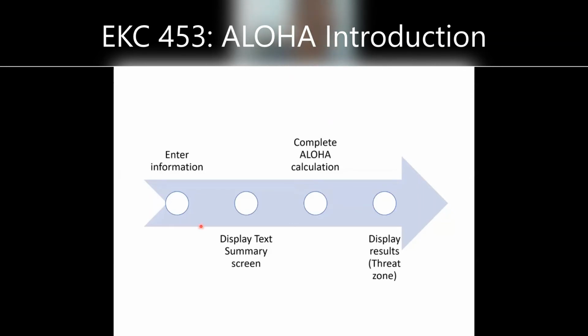If you are interested, or if the chemical you want is not listed, or the product of your plant design is not listed in the library, you can introduce or modify it. You can add other information for that chemical so that you can use it in ALOHA. ALOHA will determine whether, if there is a gas dispersion, it is a light gas or a heavy gas.